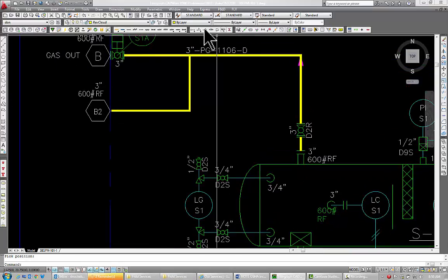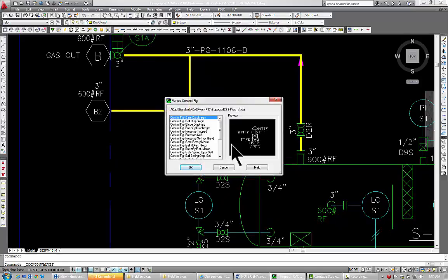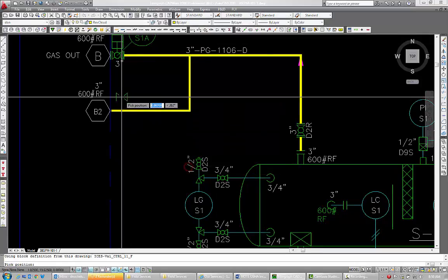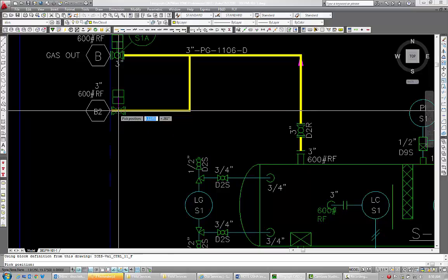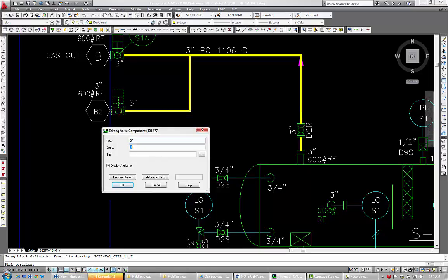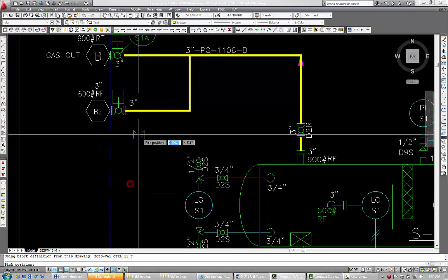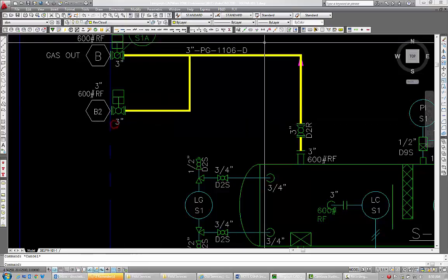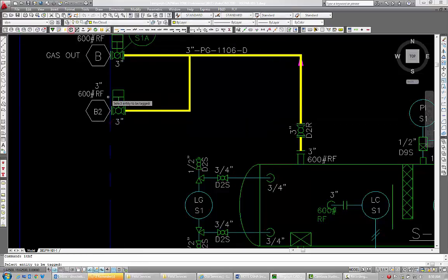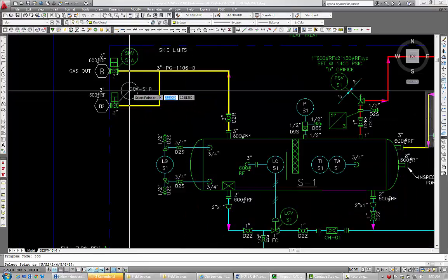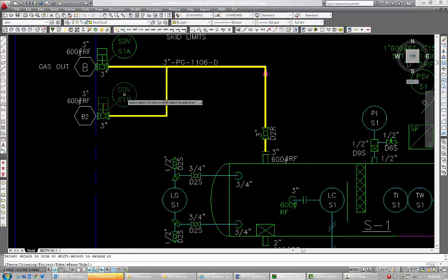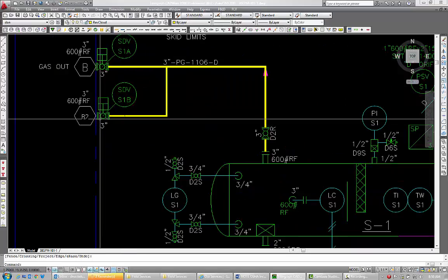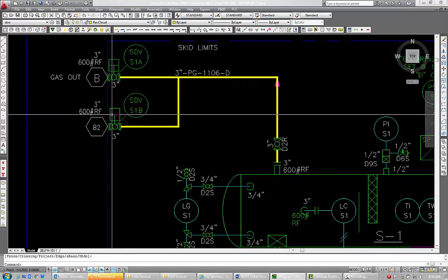Next, we're going to place another control valve, or SDV valve, at this outlet. We type in the tag. Move the size over to the location like the other one, and then quickly add our new IntelliTag as well. These IntelliTags are smart, so if the database is updated, they can be updated in the graphic environment as well.